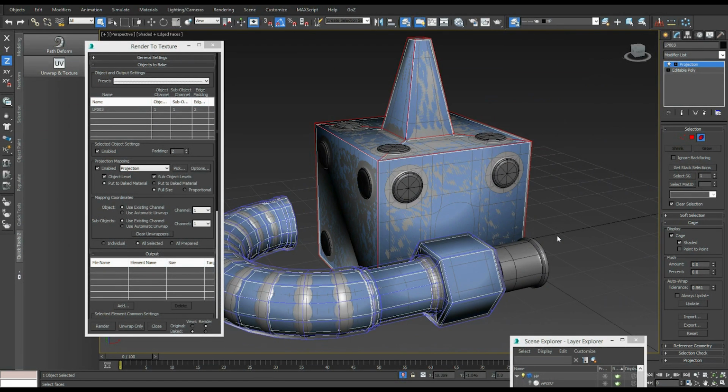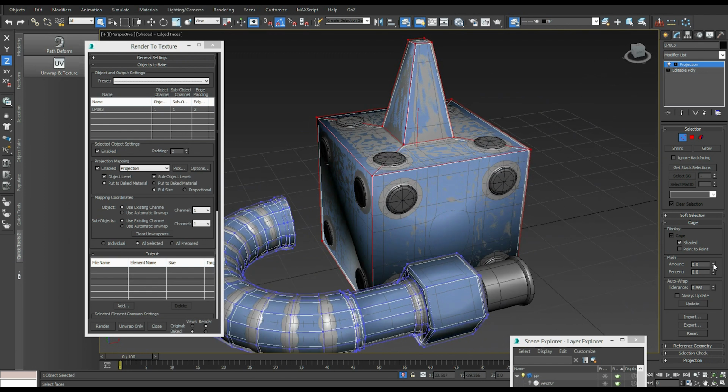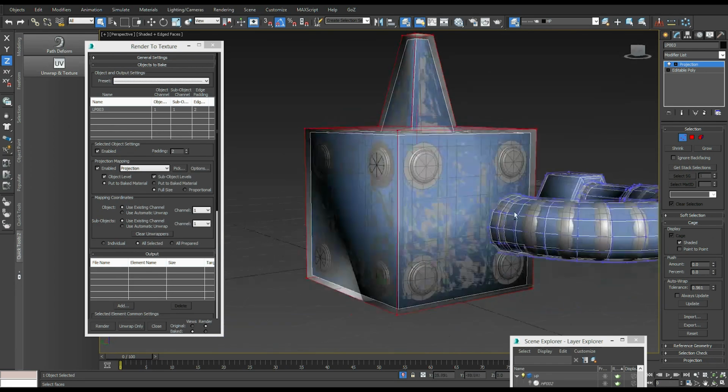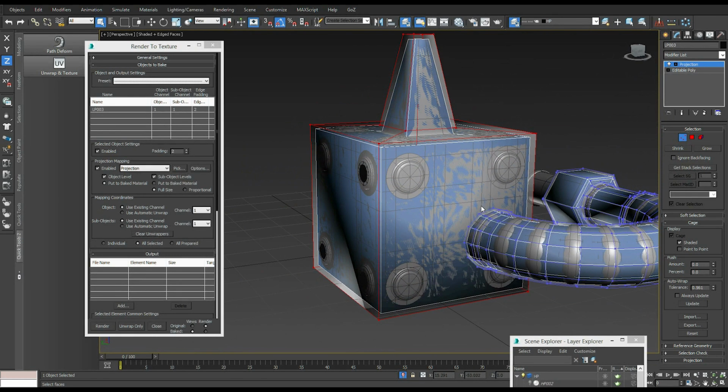The next step is I'm going to hold down Control, and while I'm holding down Control, I'm going to click the vertex part, this cage right here. What that does is allow me to push this section out on its own by itself, which I'm going to do right now. We'll come back down in here and push this out. So that's a quick rundown of how you want to set up the cage. And it looks like this part might even still be, yeah, there we go. Something like that.